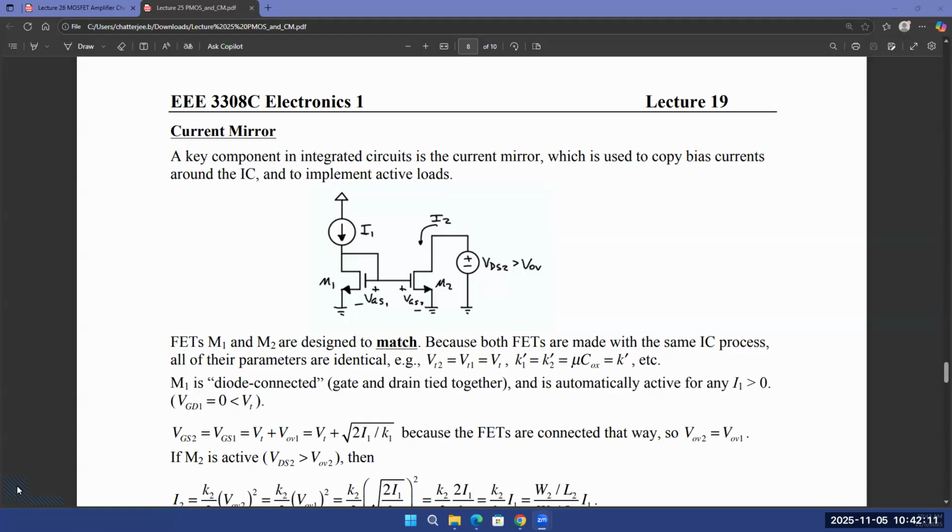We have looked into multi-stage amplifiers, that if you have multiple of those stages, common source, common gate, common drain, and arrange them in different fashion, you can get more gain out of the system, because you eventually cascade amplifiers. We also started looking into current mirrors, because in the example problem that we were solving in the last lecture, you saw that there were three current sources. That's basically your homework number 6; when you solve that problem, you'll see that there are 3 DC current sources in that circuit.